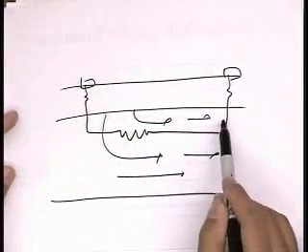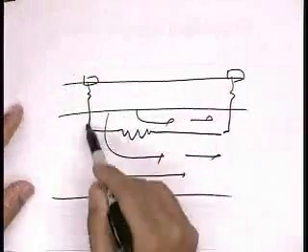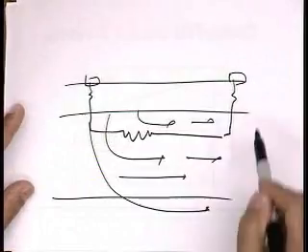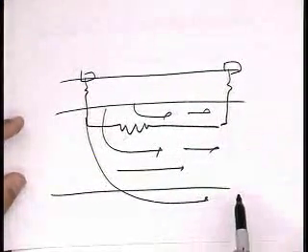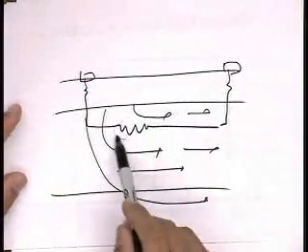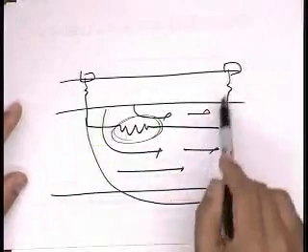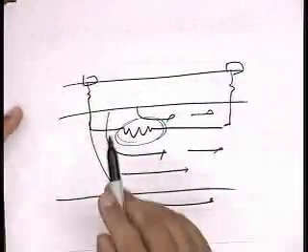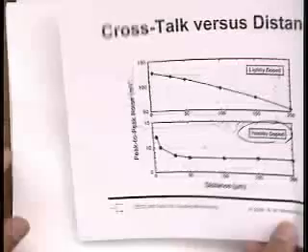The further out I go, the deeper the current can go, and that changes things a little bit, so I go a little bit away from linear. But for the most part, because this is an important fraction of the total resistance connecting these nodes, increasing this does improve the isolation. Okay?